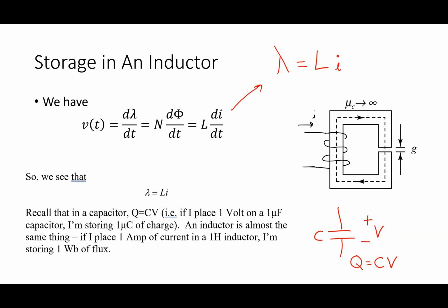The other thing is, unlike a capacitor, Q equals CV. For pretty much any capacitor, Q equals CV always. For an inductor, the inductance changes if the I gets to be too big. All right, so that relationship, lambda equals Li, breaks down fairly easily. So they're ugly to deal with. All right, so there's a couple of reasons, but inductors are really important in motor operation, generator operation. So we got to focus on them.